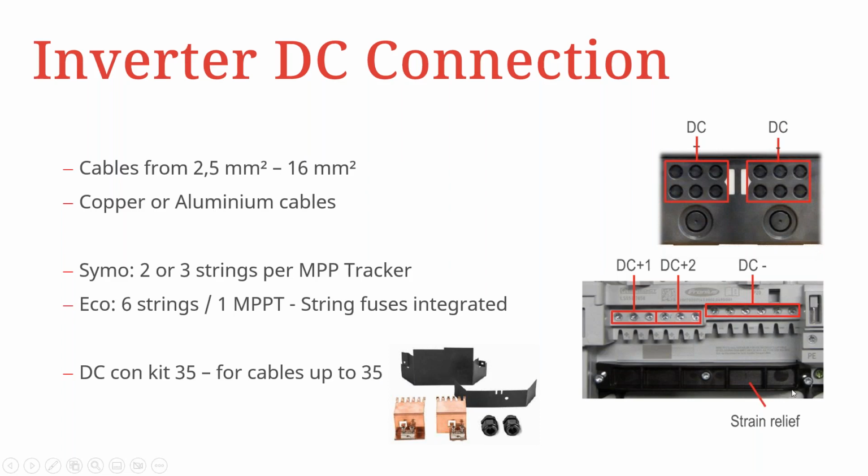An important note is to always still use the strain relief on the inverters, as well as on the old SNAP inverters. You would notice the old string inputs if you are doing direct. But if you're doing pre-combined, you are allowed to drill out this section and then simply fit a gland for the cable that you're doing for the pre-combined.